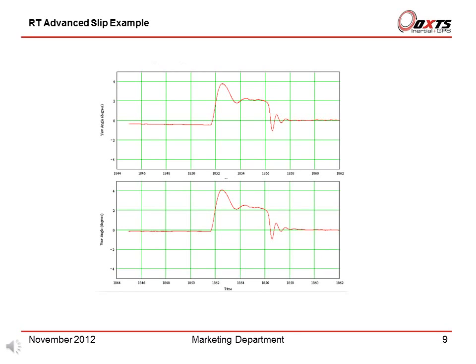At the end of the test, the acceleration of this test has enabled the Kalman filter to correct the heading drift. The bottom graph, with advanced slip, has a much smaller heading difference between the start and the end of the test, about 0.1 degrees. Here the advanced slip is operating correctly during the straight lead-in to the test, and the heading is kept accurate. During the test, the advanced slip turns off automatically to prevent real slip angles from upsetting the heading.